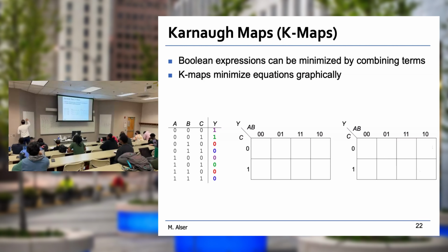So our table should be, since we are splitting the inputs, which we call A, B, C, we split A, B on one side, and the third one on another side. And remember, this order is extremely important. We don't say C here and A, B over there, okay? So A, B, the first 2 variables, on this side, the third variable on another side, okay? How many permutations for those 2 variables? We said 4, right? So we need to split this into 4 boxes. Now, since we have another variable that could take 2 options, either 0 or 1, we need to duplicate that. Okay, now we have 8 permutations.